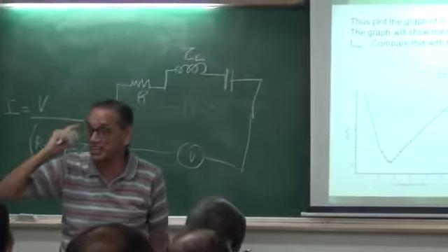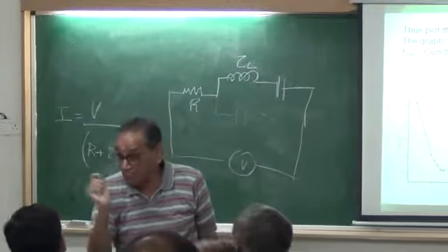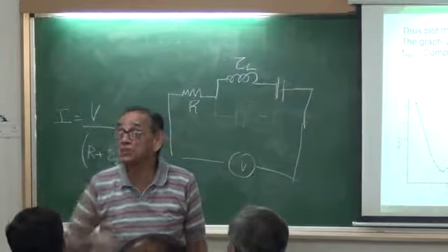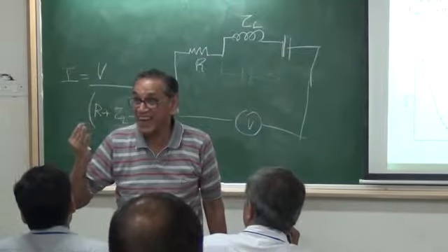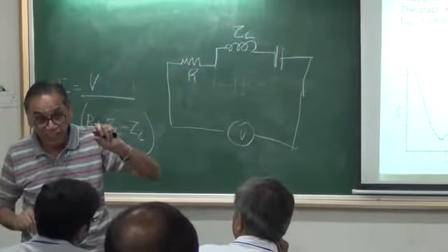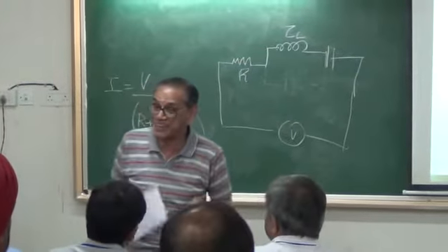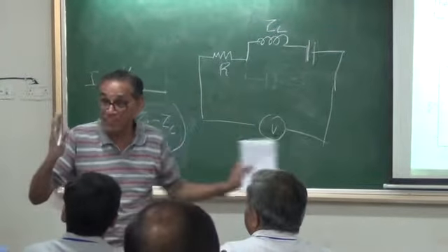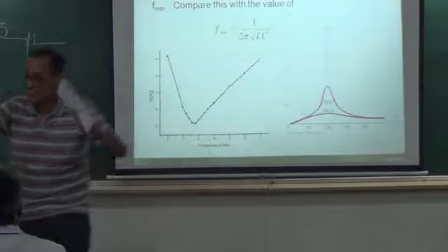But if you go to very high frequency, then your coil and resistor values will change because of skin effect. At very high frequency, your current will flow only through a layer close to the surface, not deep in the material. So the inductance will change, it will not have the original value. So we limit ourselves only up to 7 kilohertz. We don't go more than that. Okay?